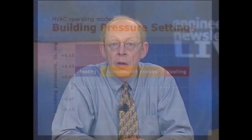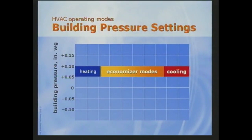And controlling to the same pressure year-round may not be the best solution for all buildings in all climates. Sometimes it might be better to change the set point range as operating mode changes. For example, when it's cold and dry outdoors, a neutral or slightly negative building pressure may be desirable to prevent exfiltration of moist indoor air.